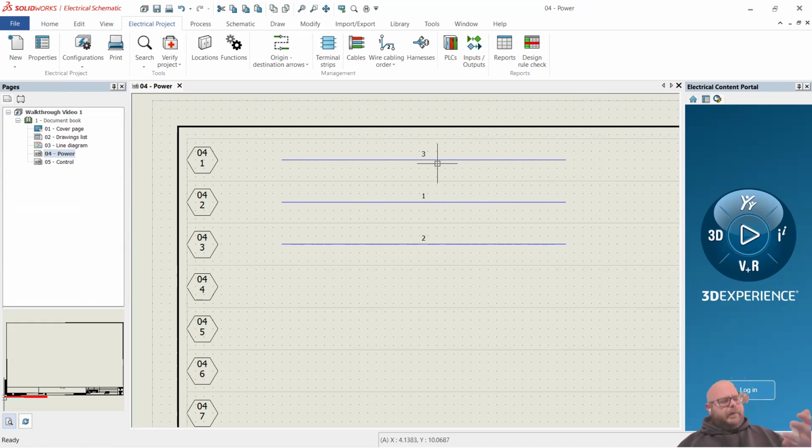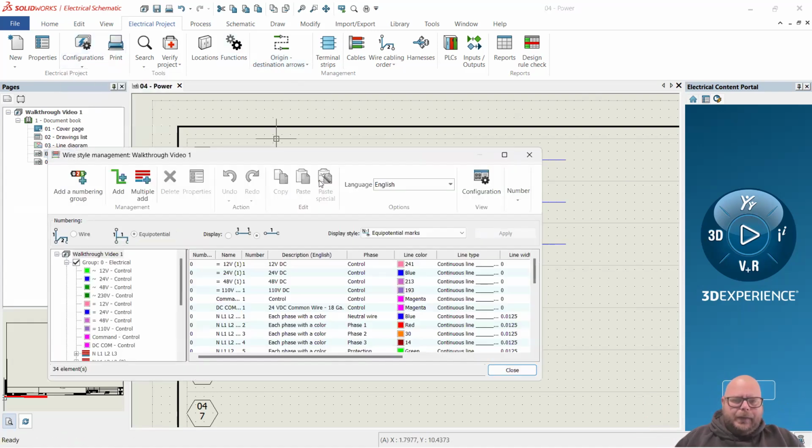That way, if I've got a schematic book in my hand and I'm staring at an electrical panel, I can match up wires, find them on the schematic. Everything's cleaner that way, right? I don't know where wire three is on the page. So I want these to be numbered page number, wire number, right? Page number, line number, I should say. And that is in that configuration, in that formula.